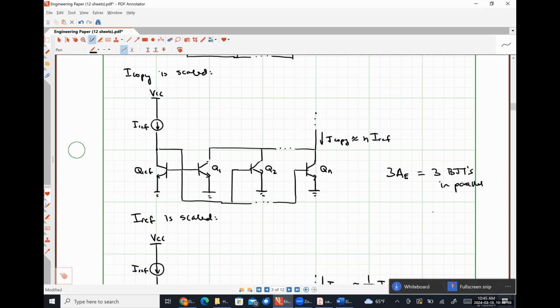So you have Vn is equal to VGS1 plus the voltage drop over this guy. Okay, so I agree with that. What I don't agree with is that the voltage drop over this guy is just gm VGS1 times R3 in parallel with R01, for a couple of reasons. A, R3 isn't in parallel with R01 because that's not ground. Also, you're not taking into account that the current flowing down through this guy is going to be gm1 VGS1, but it's also going to be V out minus the voltage at this node divided by R naught 1.